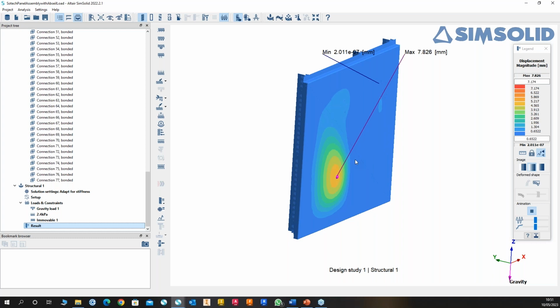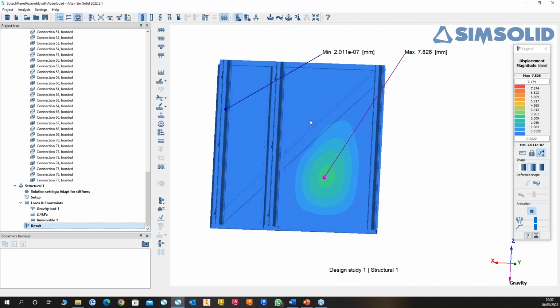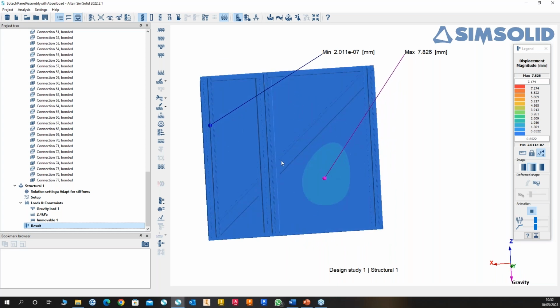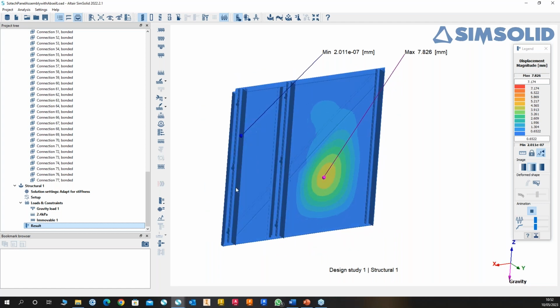And obviously then you look at the CWCT recommendation, the L over 90. Measure between your fixings, divide that by 90, and see whether that's going to satisfy the L over 90 rule from CWCT. Or if not, then you need to have a look at the stiffness. So in that case, it's fine. But if that wasn't fine, we'd probably be looking at an extra midpoint support there, or an extra chevron just running across here, or just a standard horizontal stiffener, whatever would work best.